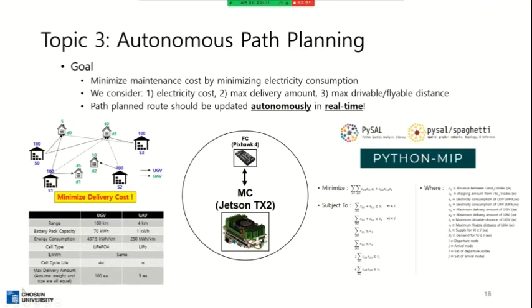The thing is, when I do the path planning based upon the energy issue, since I have some experience working in the battery industry, I'm considering the battery characteristics, which means I can model the secondary battery as an electrically equivalent circuit model, which uses about five variables, including resistors, capacitors, and so on. So I can model how the secondary battery works. The dynamic equation of this kind of battery pack is modeled and considered in this path planning algorithm. Is that the answer to your question?